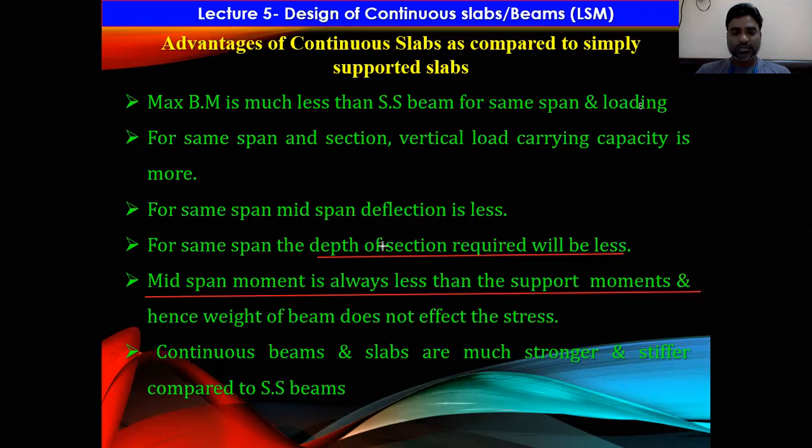Whatever I just showed, the midspan moment is always less than the support moment, right? Hence, the weight of the beam does not affect the stresses, because at the support the bending moment is more, and the support will take care of all these things. And at the midspan the moments are very small, therefore you will get a very small depth, so the weight will be reduced.